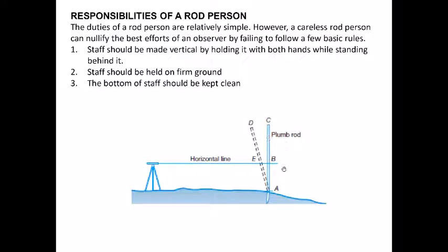The person holding the leveling staff needs to make sure that, one, he holds it from the sides so that the reading is not hidden behind his fingers. Two, he needs to hold the staff vertical. That is because if the staff is inclined forward or backward, the reading would change. So what would happen if the staff is inclined forward?